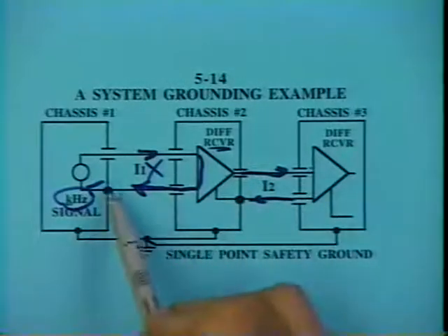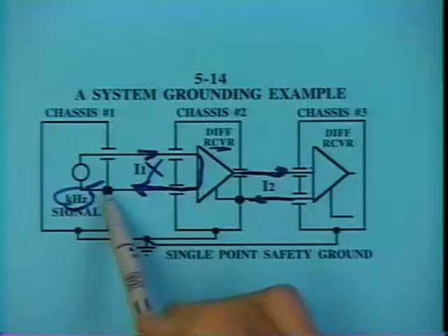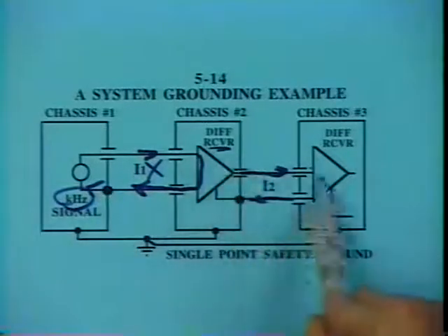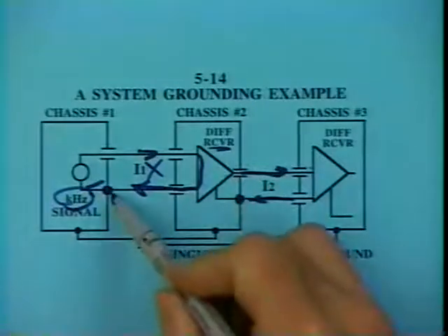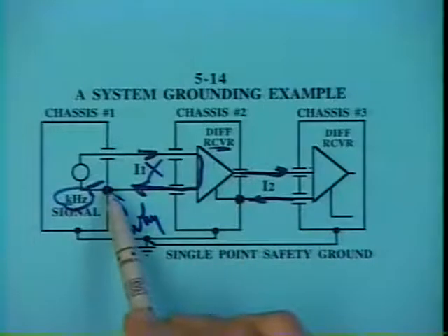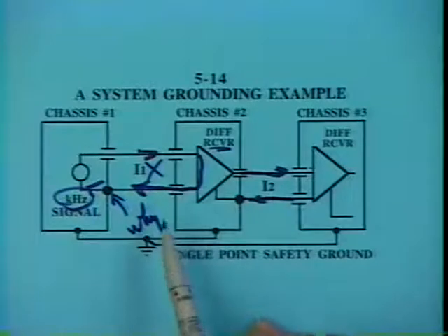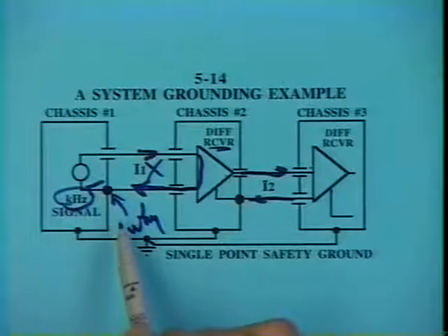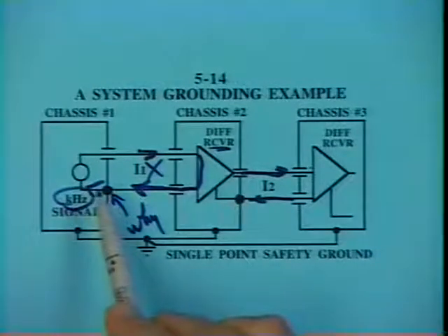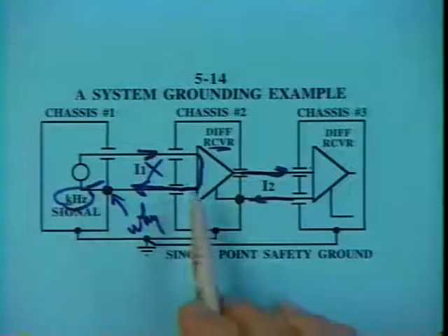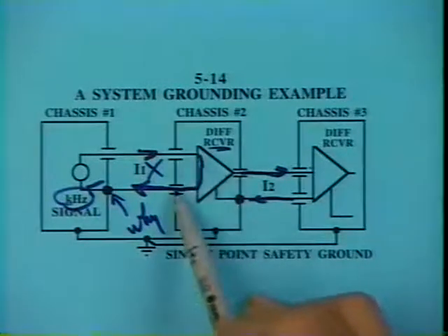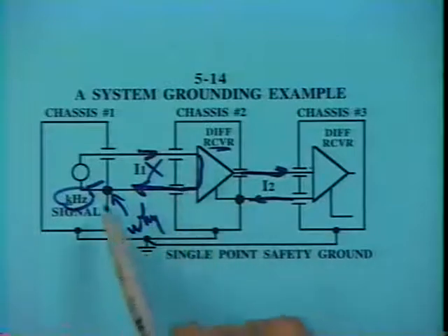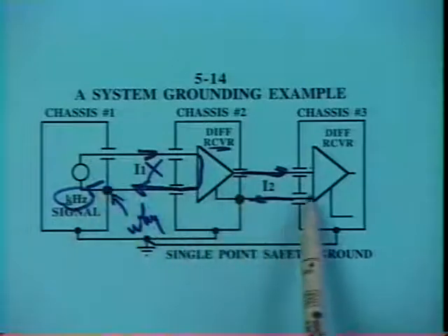Now, there are grounding connections shown. There's a grounding connection shown on the input signal here, and there's a grounding connection shown on the amplified signal here. Now, why we chose, say, grounding the signal at this location rather than grounding it, say, on the other end, that's a good question. I'm assuming probably that this was a grounded transducer, that I didn't probably have a choice in this matter of where to put the grounding connection. And again, it's usually easier to have a receiver be isolated from ground. In most instances, that's easier than having the driver isolated from ground.